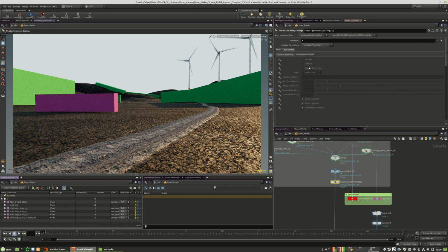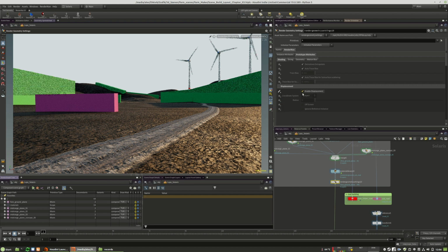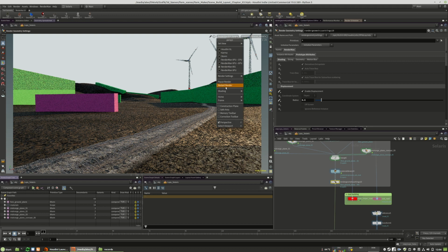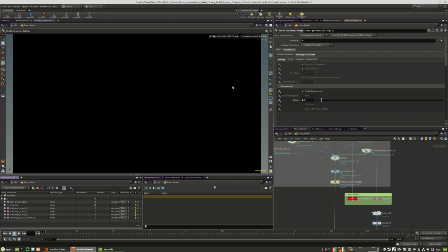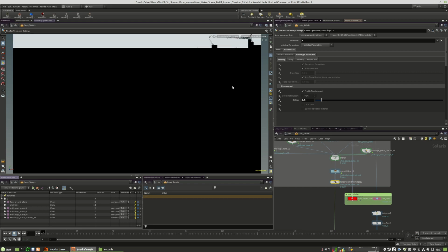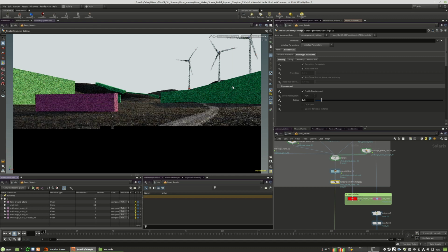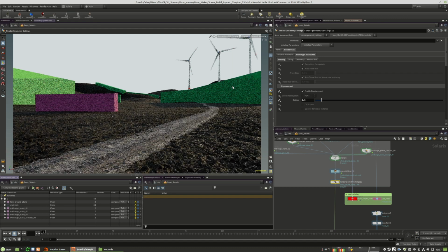We go to the RenderMan tab, to prototype attributes, and here we will set or create the displacements, and here we also need to raise the radius for the displacement. We even could make it something like 0.5, and then we have to restart the render. And now we should get a proper and good looking displacement. And you see it's rendering really fast, and it looks much more realistic, and yeah, it looks really nice.